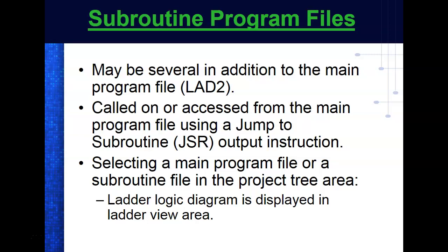So back there on that robot, anybody that has robots, that robot does several tasks, and it's all written in subroutines. So when the robot was over here, they taught the points, and when they moved the robot over there, it missed the points. So instead of me trying to find it, I would find the subroutine where it picked up the block, and I would teach that point.